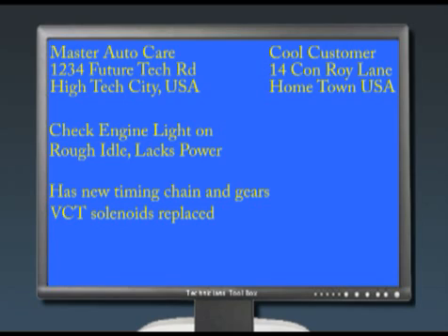just started running bad. Technician grabs a scan tool, runs out to the truck, and retrieves the trouble codes. He's got a P0012 and a P0022, intake camshaft position timing over-retarded, bank 1 and bank 2.